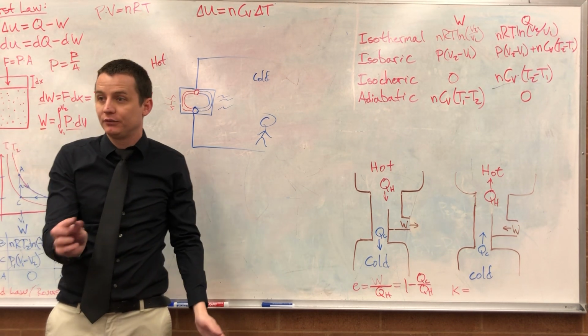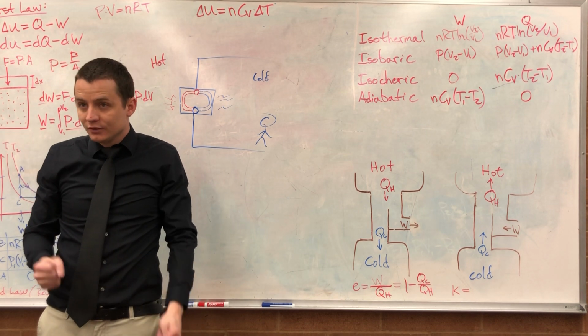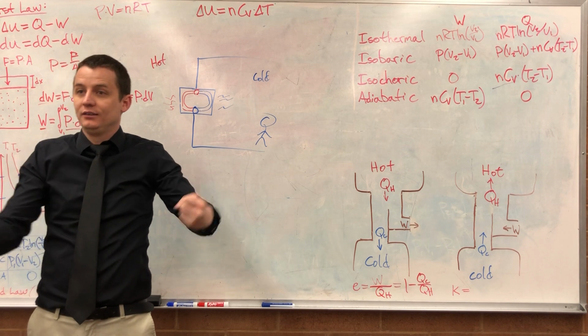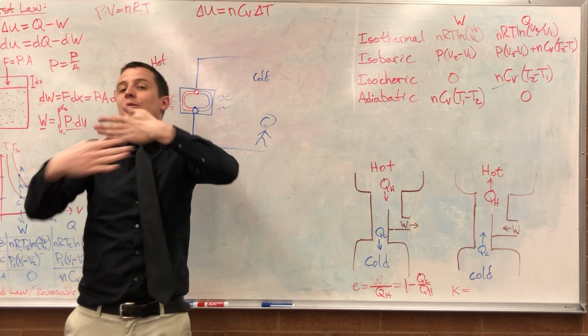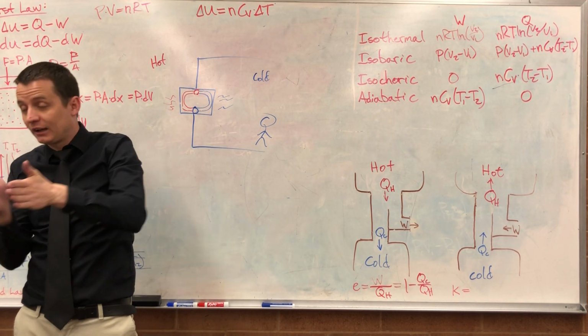You'll notice on the back of your refrigerator, there's a bunch of tubes going back and forth. There's just a liquid in there that's being compressed and then expanded. It's being allowed to expand when it's inside the refrigerator, inside the insulation, and when it's outside, the part that you see, is when it's compressed. And so it's actually hot on the back.